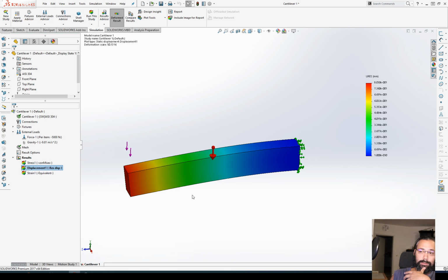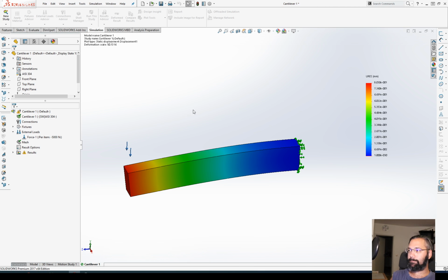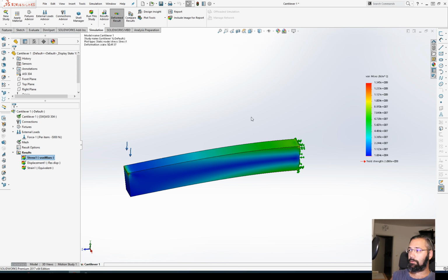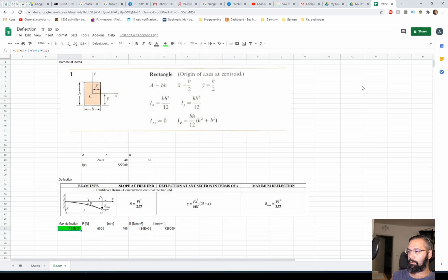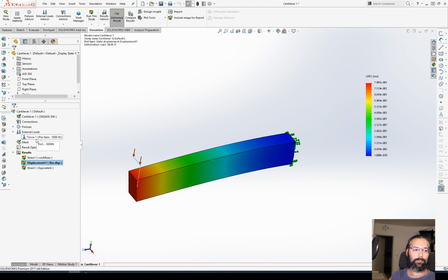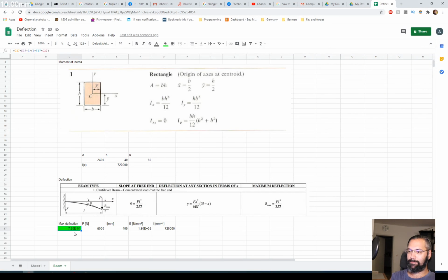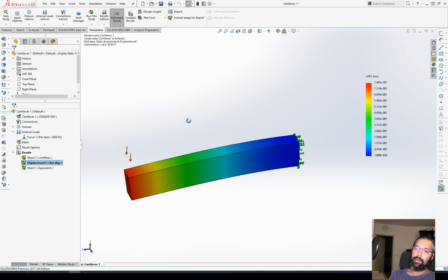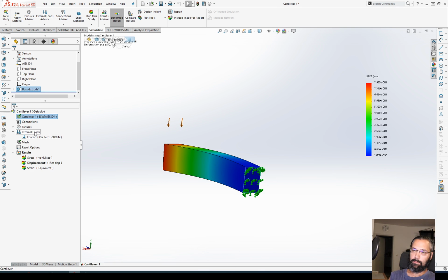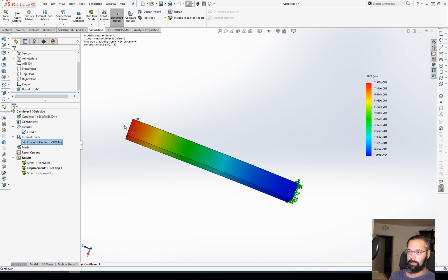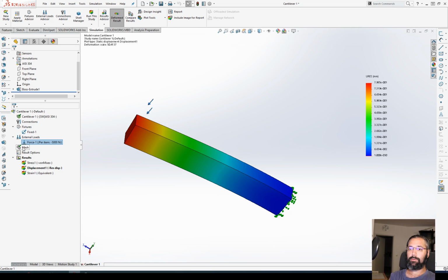So this is how you do your simple beam analysis. Maybe this is why. Yeah, this is for sure why. The gravity wasn't in the calculation. Of course it wasn't. I added the force and then I'm like, oh, why is this different? But it's still different by less. So this fixture says this is fixed. This force says there's a force applied in a direction I chose.